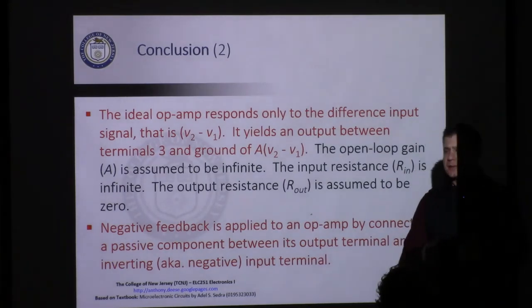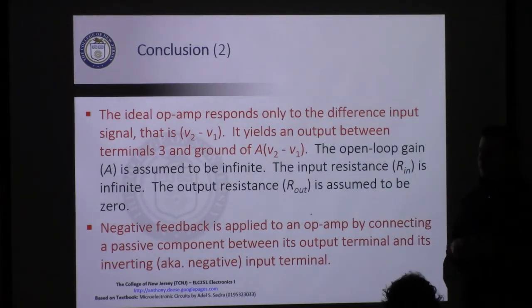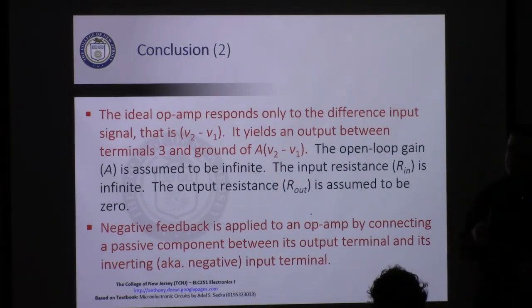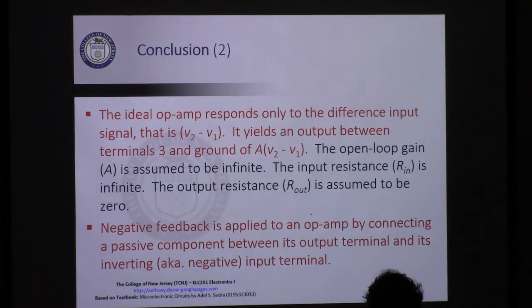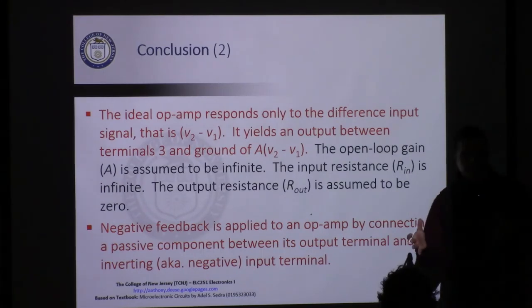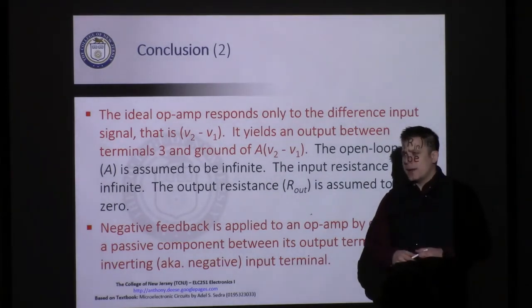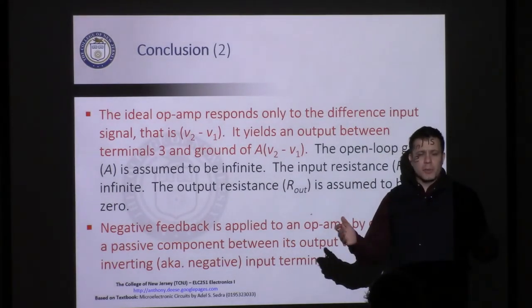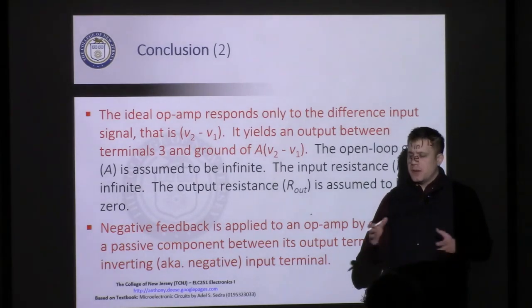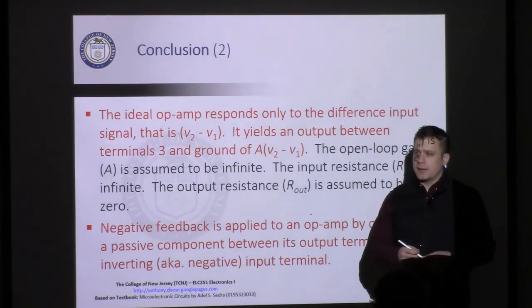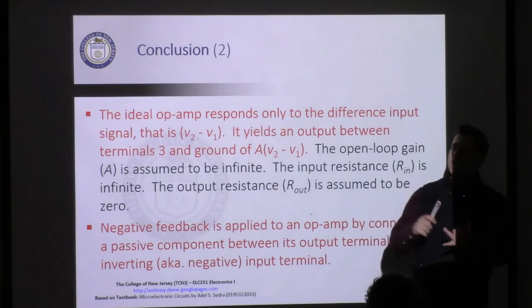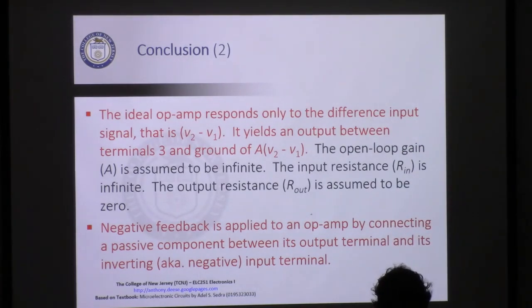So we spent a lot of this chapter talking about negative feedback, both about different configurations that employ negative feedback, summing amplifier, inverting, non-inverting. The integrator also utilizes negative feedback, the difference amplifier, instrumentation amplifier. And then we talked about how to look at a configuration that employs negative feedback and calculate the closed loop gain. Right? So let's say we are not familiar with a configuration. We know the steps in order to calculate that. That involves a virtual short and the assumption that the bias current is 0.